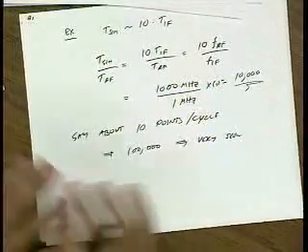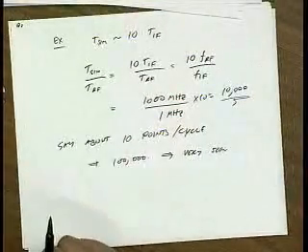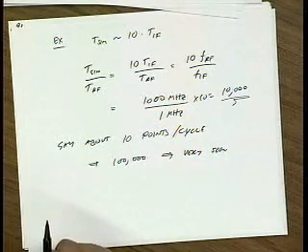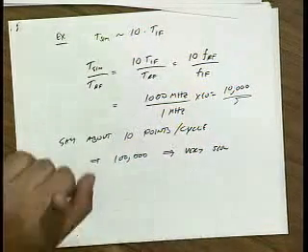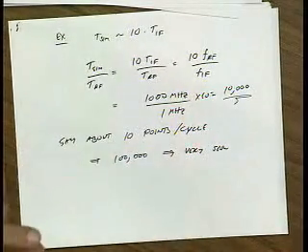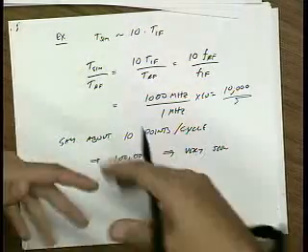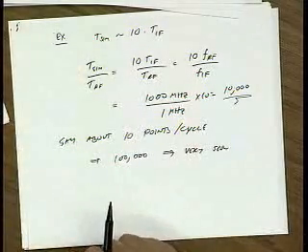Okay. Now the same exact problem happened when we look at IM3, right? IM3 has the same exact problem. If you have two tones that are close together, the IM products are also going to be very close, and so the same kind of analysis applies. Okay. So this is why nobody likes to simulate mixers with transient.